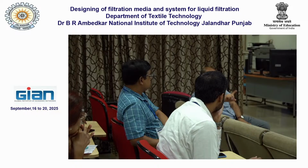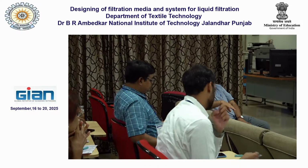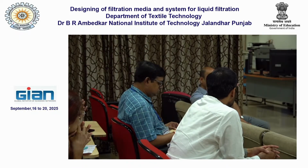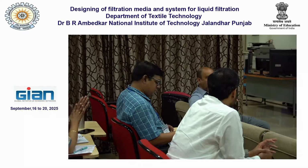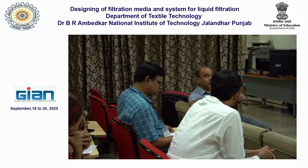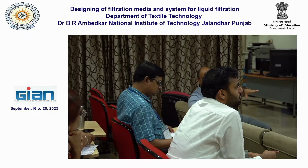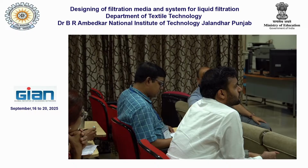So that will be purely a membrane. But if you are making the membrane by electrospinning, for example, then it comes into the textile category, because your making process is fiber. First you make the nanofiber, then from the nanofiber you make the membrane. So a membrane can be textile based, and it could also be non-textile based. Both are possible. But polymeric membranes, I think we can consider textile, unless it is steel or ceramic. If it is simply a sheet, like the solvent cast method, and it is not a fibrous matter, and you are punching holes and then expanding it, then it will be purely a membrane category.